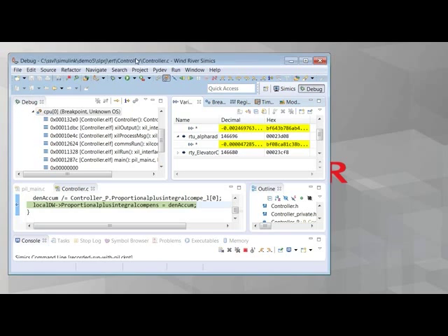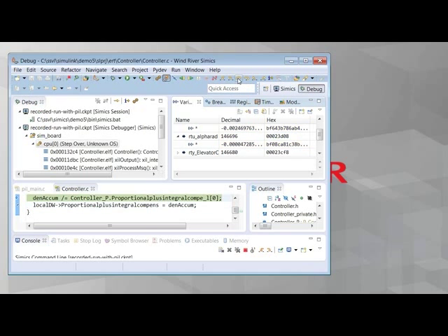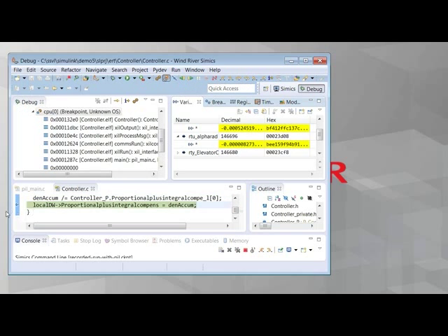Notice up until now I've been running forward through my code, clicking on the step and run forward buttons. Well, notice next to those buttons are step backwards and run backwards buttons. I can actually step backwards through my code, or even run backwards through the code. In this case, if I run back to the previous breakpoint, I can see now that my outputs are changing backwards in time. And as you can well imagine, this is invaluable when debugging.